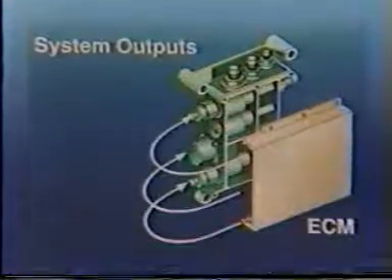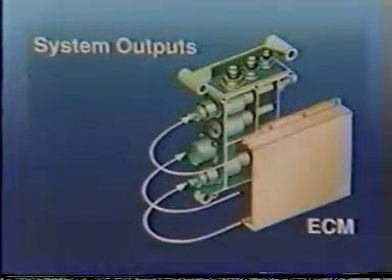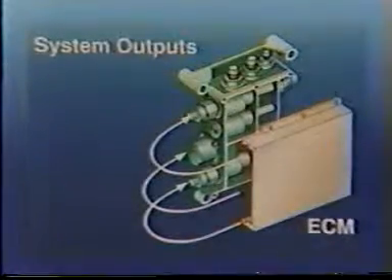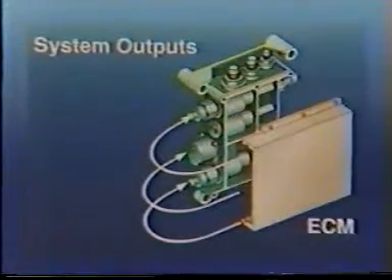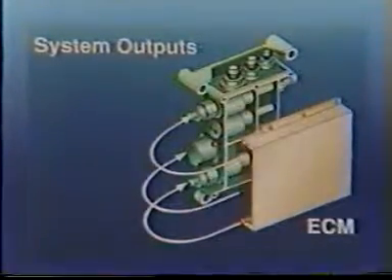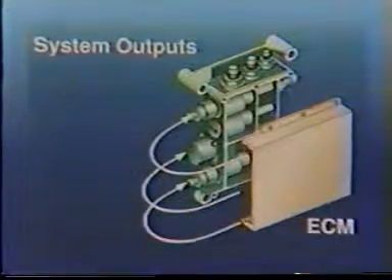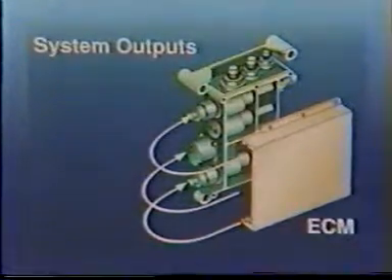There are 6 system outputs. 3 of the outputs control the fuel rail, timing rail, and fuel shutdown functions. The fuel and timing control actuator valves are spool-type valves. The spools are controlled by an electromagnetic device which is commanded by the ECM.